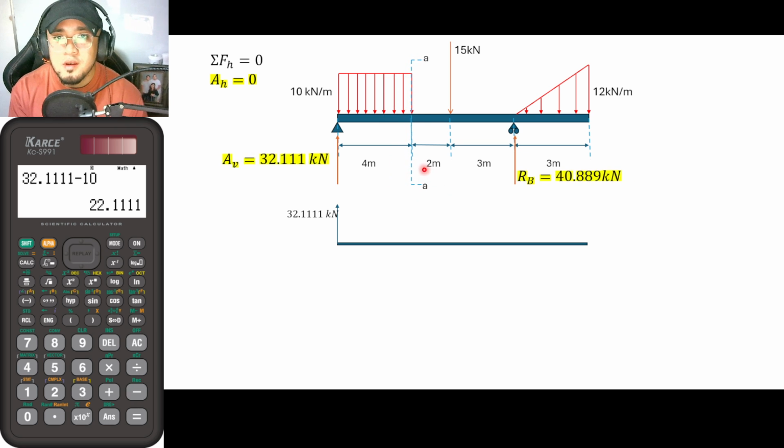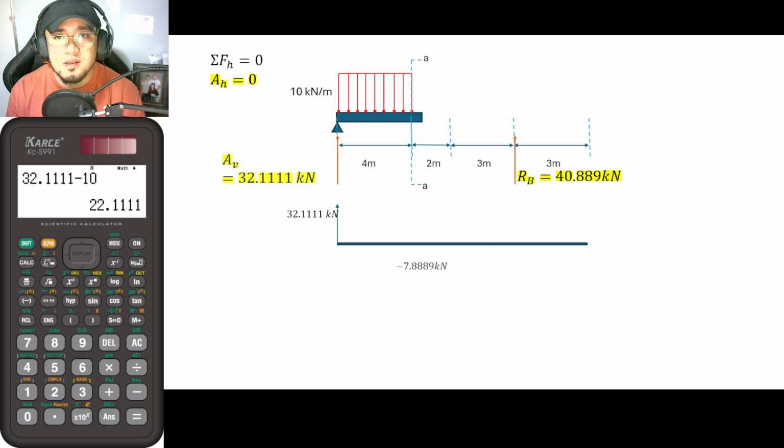Okay, so if you would be getting the section at that point, let us cut it and only consider the beam on the left and erase the right portion of whatever is here. Okay, so if you would now be getting the section here, guys, so again, summation of forces vertical, that is equal to V at A, so the shear at this point or at this section.